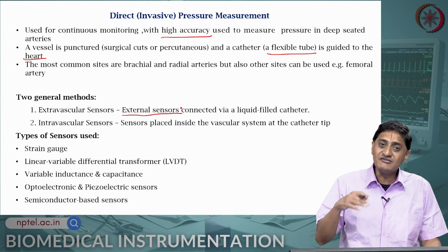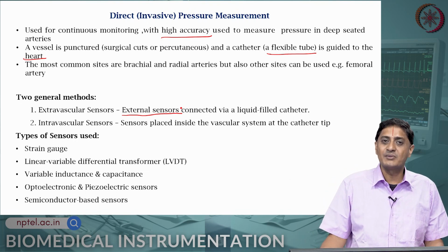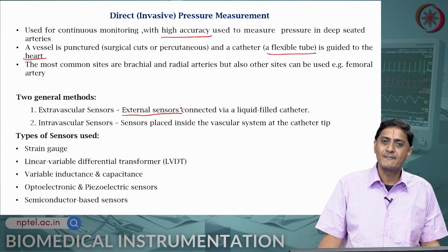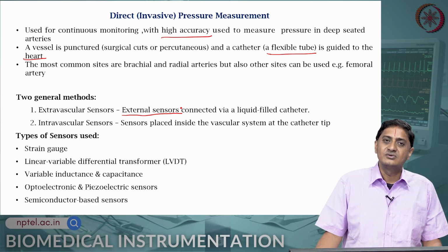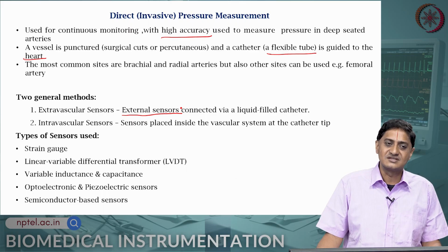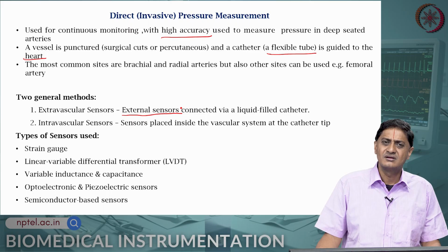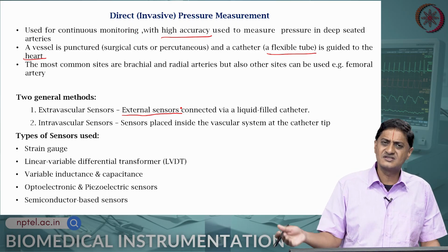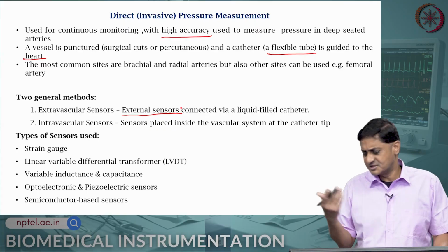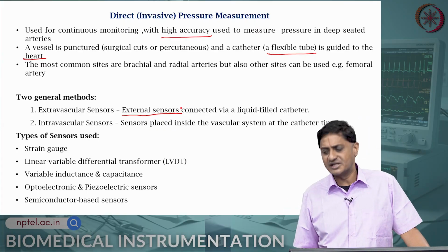The manner in which light reflection happens changes as a function of the pressure that is being applied. And then you have semiconductor based systems, that is piezoresistive systems or MEMS based systems. There are many different systems that use semiconductor approaches to measuring, in this case measuring pressure in general, as a measurement element.